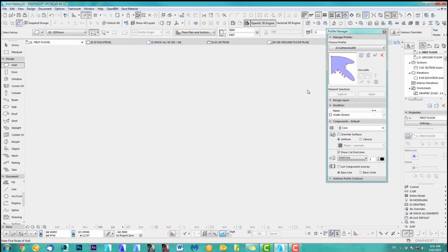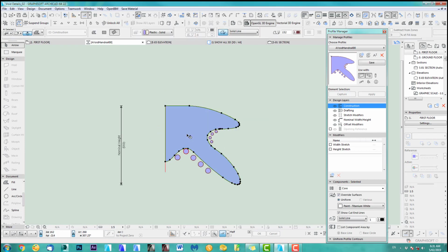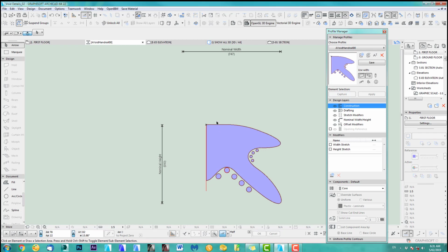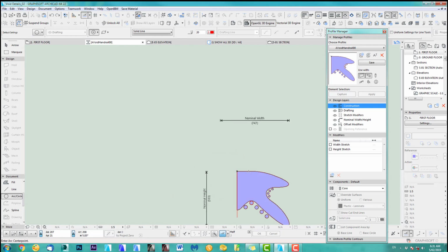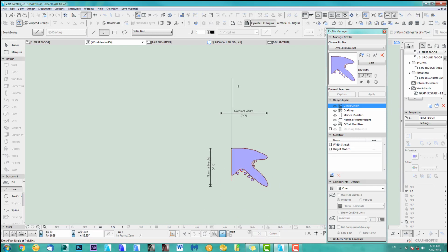Okay, edits. So obviously you don't need this stuff. So what you do is we just delete a couple of things. Actually, you know what? I've got to leave this in as a reference for now. I delete this after. So now we like to add a handrail, and we do this as an example. Again, this is just tutorial wise. I need to know the handrail is roughly 1100, so I go 1100 plus. Okay, that's the height of the handrail.